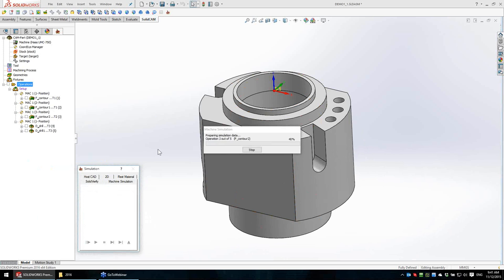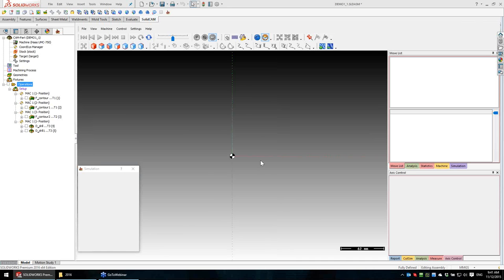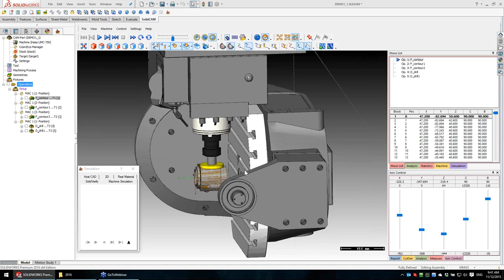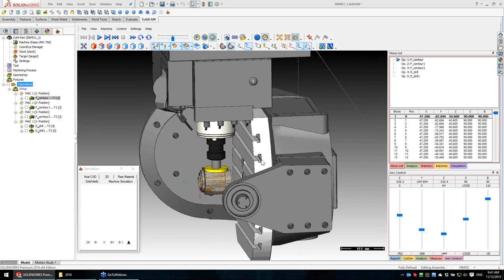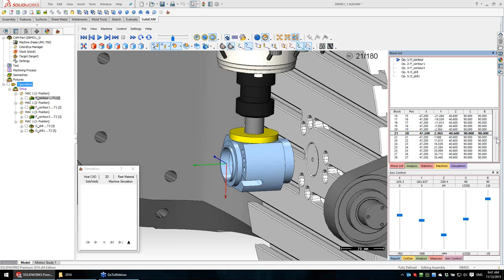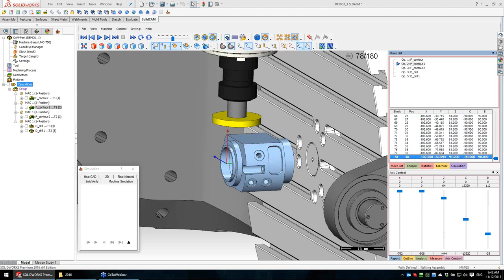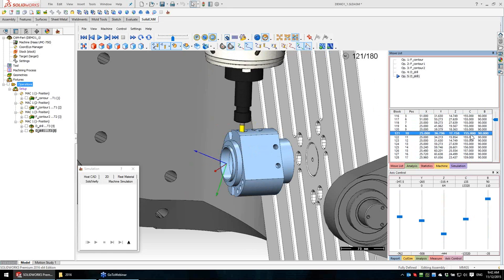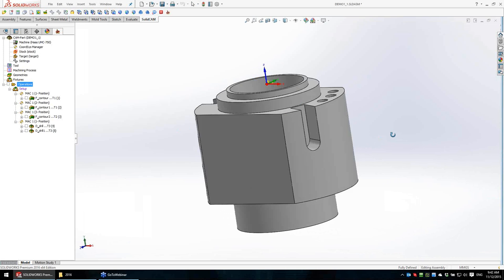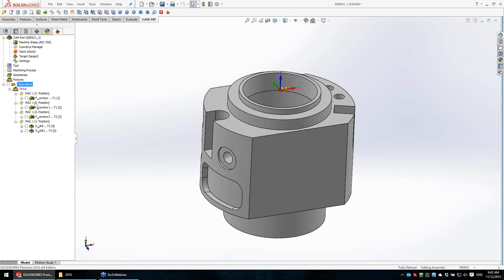And if we go to simulate, this part will work as previously. Now it is using the B-axis, tilting the B-axis to bring it to 90 degrees, and working 4-axis as in the previous machine. First operation, and the second, and the slot, drill, and drill around the 4th-axis. You can already see the progress moving parts from one machine to another. But I will show you another example.